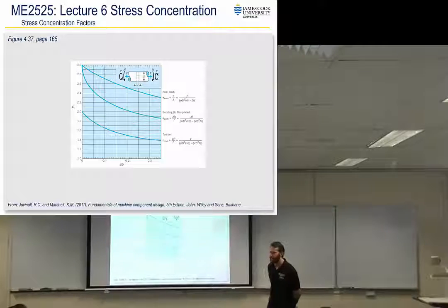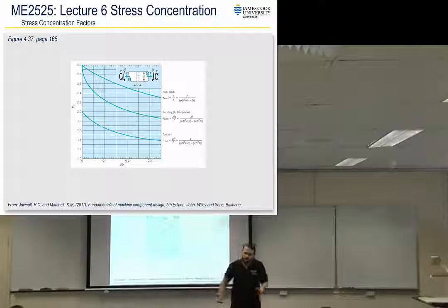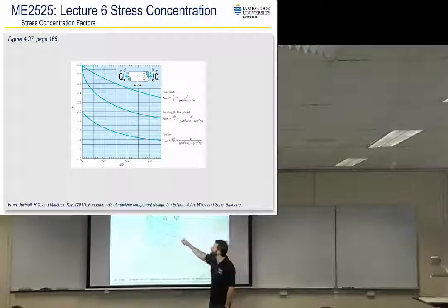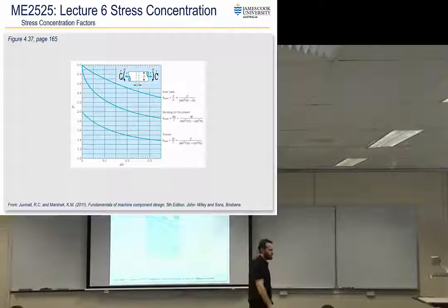When you get the maximum stress on that hole in terms of throughout the cross section. Right. Yeah, probably just on the edge up there. Yeah. So either on the base face or on the side of it. And for just to be critical, you just choose one of them and then just use the worst case scenario, the bending and torsion and everything at that point. But that point's the point where that stress concentration is going to come to bear on the maximum stresses. Okay, so you just choose a point somewhere on that edge, on the edge of the actual hole, and that would be the point to analyse.